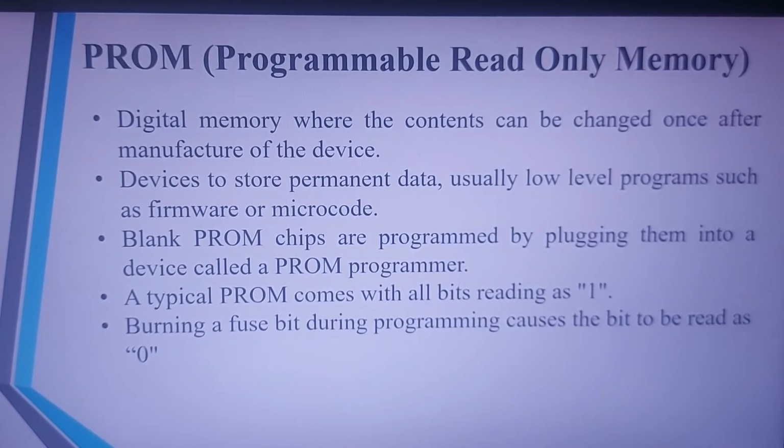Initially, by default, PROMs come with all the bits reading as 1. Then it has to be changed to 0 wherever required. By default, all the cells of the PROM will be 1 when it is manufactured. There is a fuse-like structure available, and that has to be burnt to make it 0.